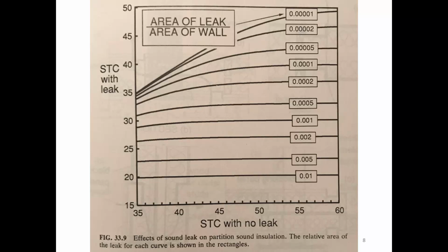So here we have this table. It's from Harris, that was the environmental, outdoor sound propagation reading assignment. That's the same author. But he publishes this table. So say you have an STC, remember the sound transmission class. So that's the one that is a single number rating for the transmission loss of an assembly from 125 up to 5,000. So if you had an STC that produced 50.